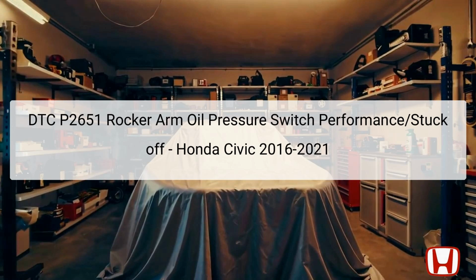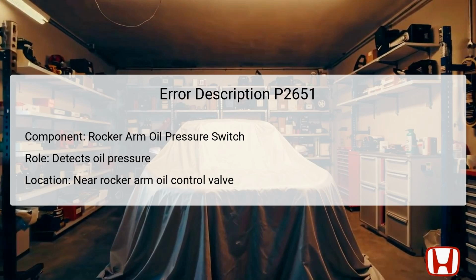Prior to troubleshooting, it's important to have the necessary tools on hand to perform accurate measurements and repairs. DTC P2651 specifically pertains to the rocker arm oil pressure switch's performance being below the required threshold, or it being stuck in the off position. This switch is pivotal as it monitors the oil pressure within the VTEC system, enabling optimal control of valve timing. When the oil pressure is too low, the switch fails to activate, resulting in poor engine performance.